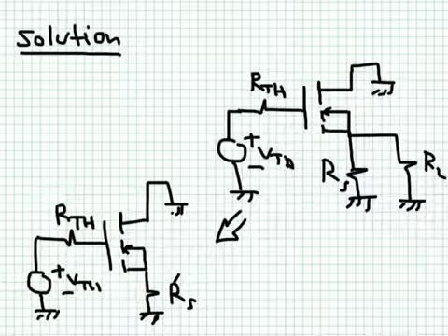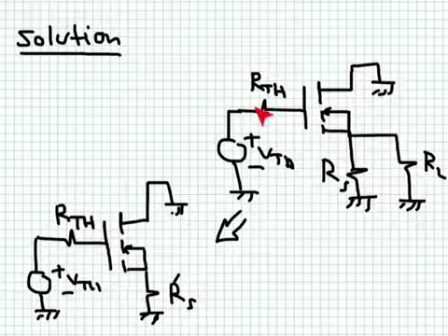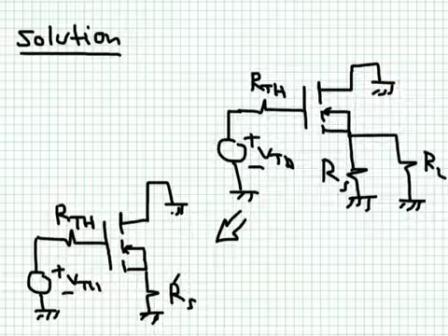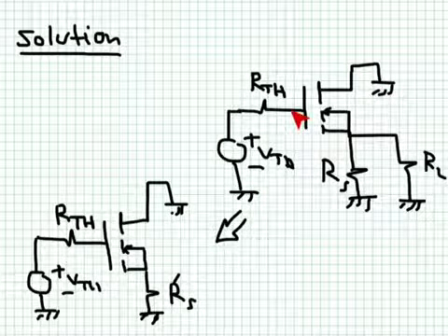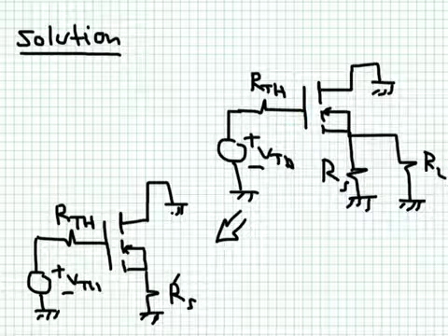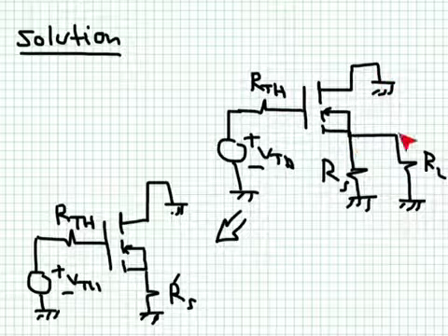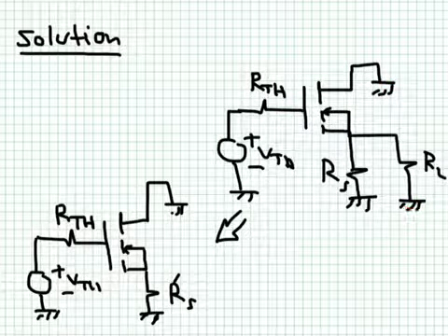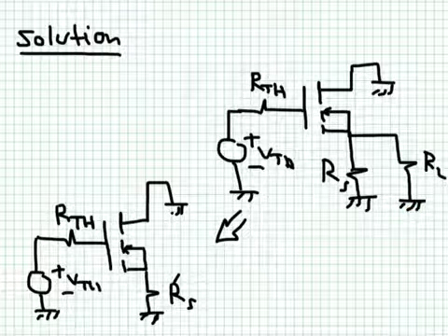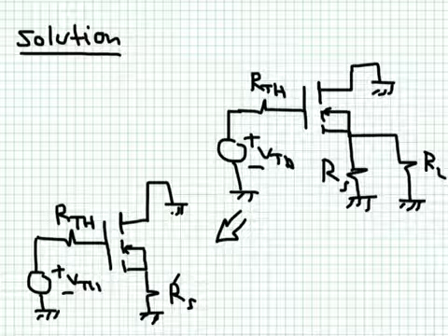Okay, so this is how the circuit looks for the AC small signal analysis. Capacitors have been replaced by short circuits. VDD has been removed, it is now ground. So now we can see the input is applied to the gate, so between the gate and ground, but the ground is really VDD. The output is taken from the source and the ground, which is connecting the RL, but ground is VDD. This is why we say that it's called a common drain. It's a common drain amplifier.